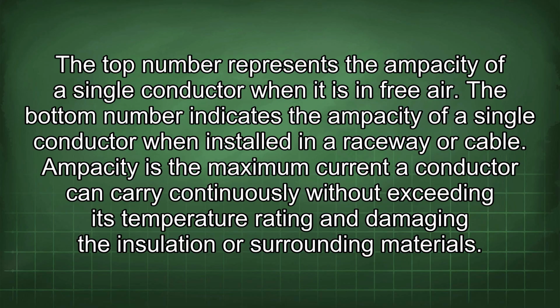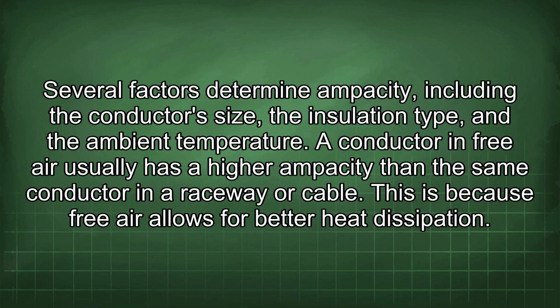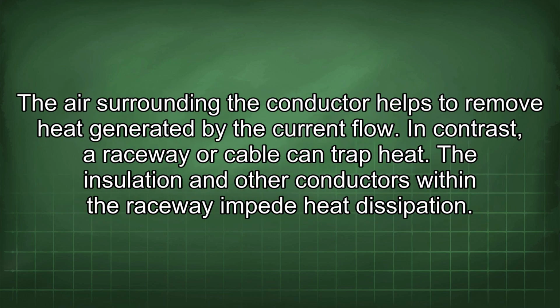Ampacity is the maximum current a conductor can carry continuously without exceeding its temperature rating and damaging the insulation or surrounding materials. Several factors determine ampacity, including the conductor's size, the insulation type, and the ambient temperature. A conductor in free air usually has a higher ampacity than the same conductor in a raceway or cable. This is because free air allows for better heat dissipation. The air surrounding the conductor helps to remove heat generated by the current flow.